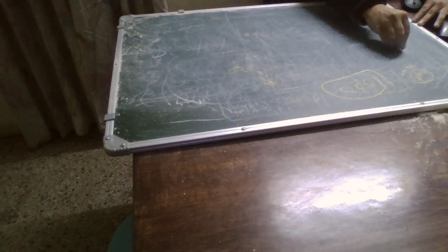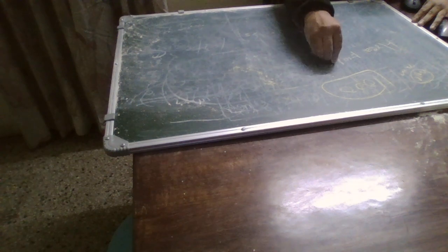The next thing that we need to decide is the wire size. I have mentioned that we are going to see what power handling ability or capability we need. So what we first decide is the area product, called AP, and it is equal to the window area, WA, times the cross section area, AC.